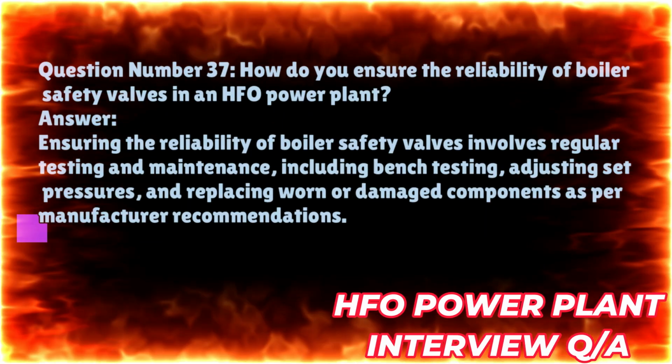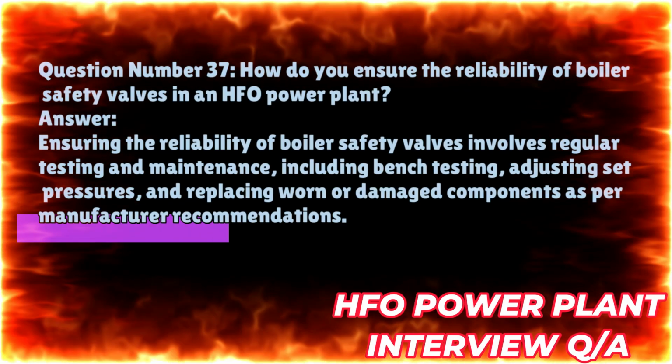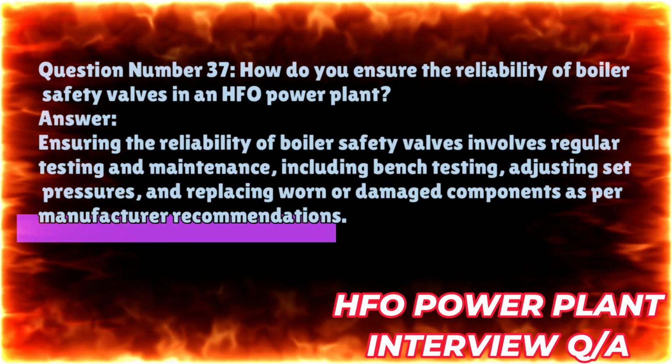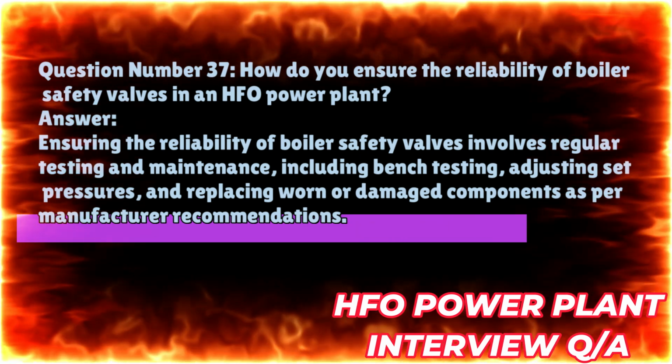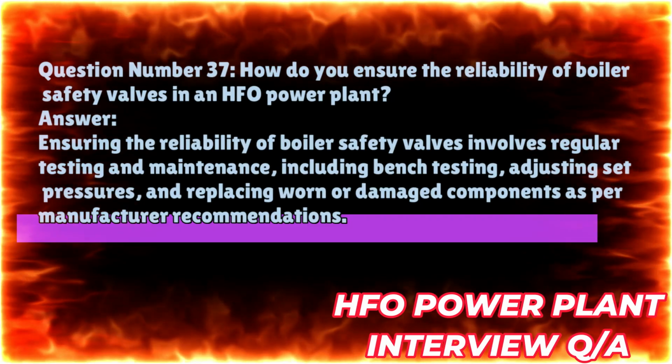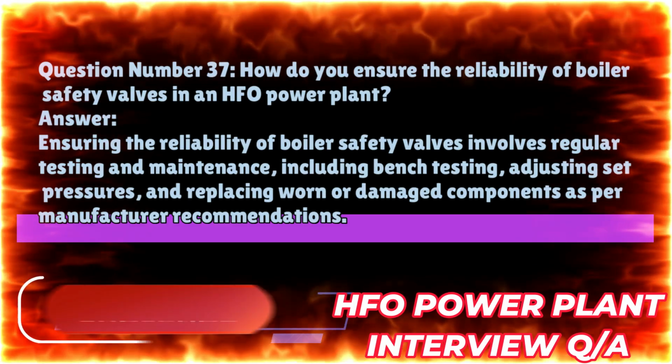Question number 37. How do you ensure the reliability of boiler safety valves in an HFO power plant? Answer. Ensuring the reliability of boiler safety valves involves regular testing and maintenance, including bench testing, adjusting set pressures, and replacing worn or damaged components as per manufacturer recommendations.